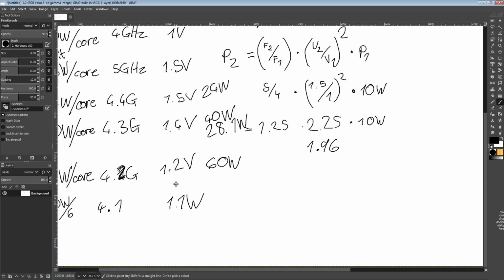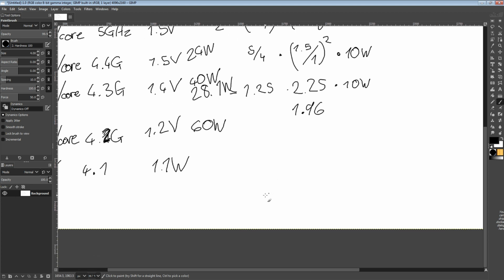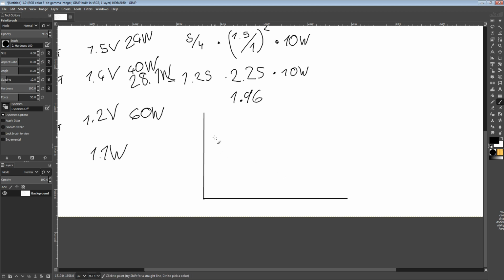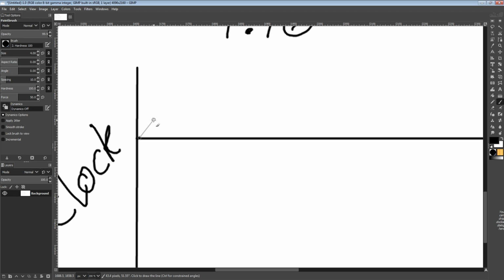And the funny thing is, the thing that I don't personally like about AMD's boost algorithm is that if you actually take an oscilloscope and monitor the behavior of the algorithm on, say, single core workloads, you're going to see something, with time on one axis and clock on the other, where instead of holding a nice steady clock speed, it'll constantly do silly things, or at least what I consider silly things, where it'll do something like that, right?